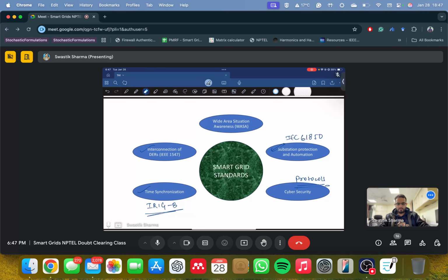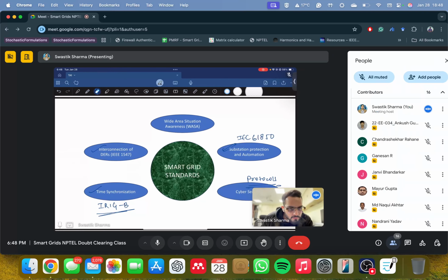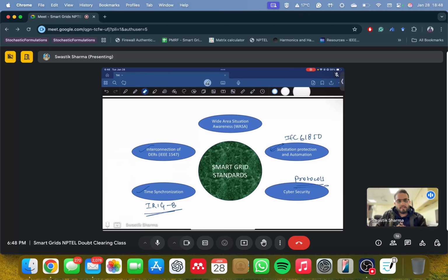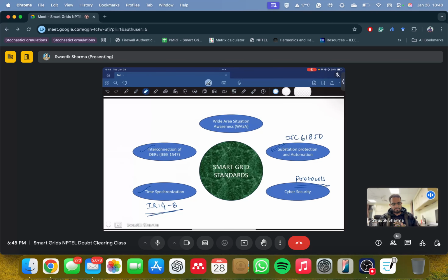Now, what is wide area situational awareness? So this term I've talked about 2 times, I feel. As I was talking to, I guess his name was Mayur, if you have a very large geographical spread, you want to be aware of the situation at all given points of time. That means you want to be able to remotely observe the different power system components. And for that, WASA is used. It's called Wide Area Situation Awareness. Here, PMUs play a central role. So this is what WASA is.